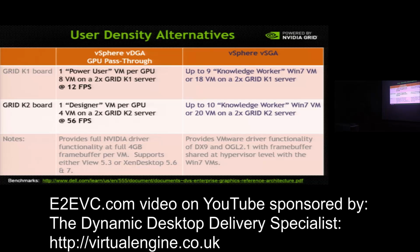This is a set of benchmarks that were done by our good friends at Dell, and they're published. You can get this document. They did some quick tests where they used Login VSI to create a user workload environment. The column on the left is vDGA, with dedicated graphics, which should give you your best experience. They ran on the GRID K1 board with 8 simultaneous users, so you've got 2 K1 cards and a Dell R720 server. They're getting about 12 frames per second running their benchmark in this mode on 2 K1 cards with 8 simultaneous VMs, so it gives you a feel for what sort of performance they're achieving. We consider that interactive graphics for a CAD user should be at 15 frames per second or higher. That's the standard we generally use for interactivity for an engineer to be productive.